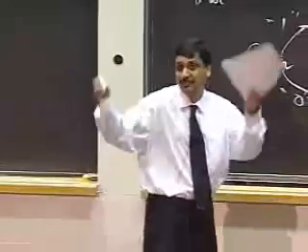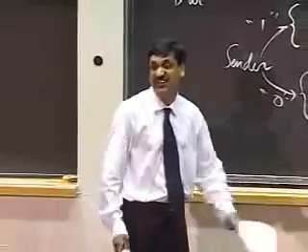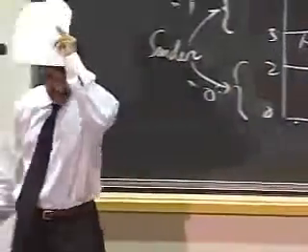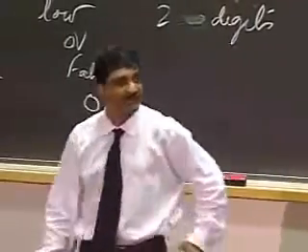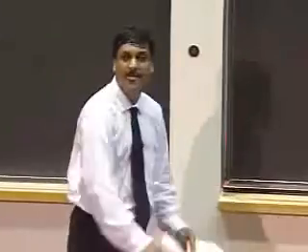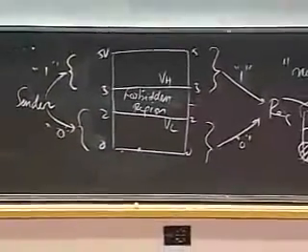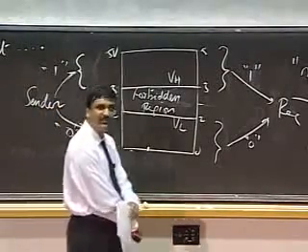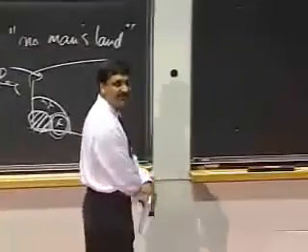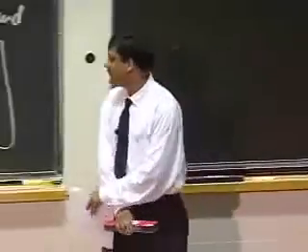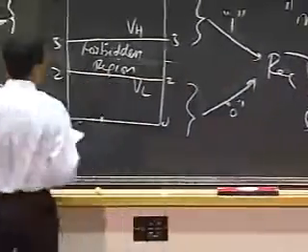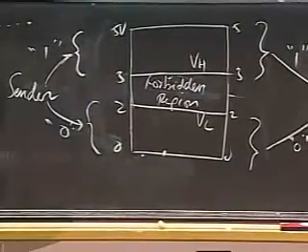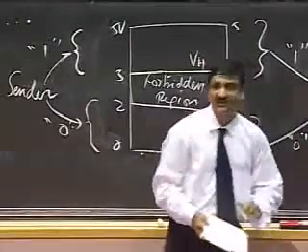That works. So you, as a receiver designer, can do whatever you want when you see a 2.5. You can say, I'll just put out a 1 if I see a 2.5 or 2.6. I'll just do something. No one cares. So this is pretty good. We still have a problem, though. Do people see the problem here? This still doesn't quite work. If Intel did this, instead of your laptops failing and blue screening every hour, they'd be doing it every millisecond. So the problem is, with this discipline, I've allowed the sender to send any value between 3 and 5 as a 1, and any value between 3 and 5 at the receiver is treated as a 1.